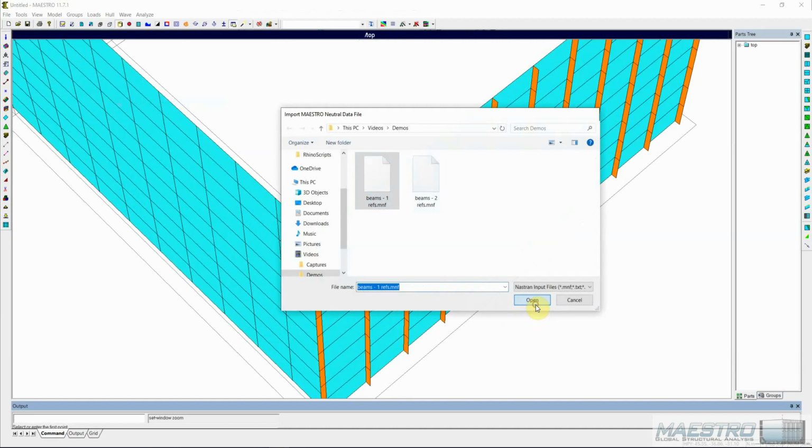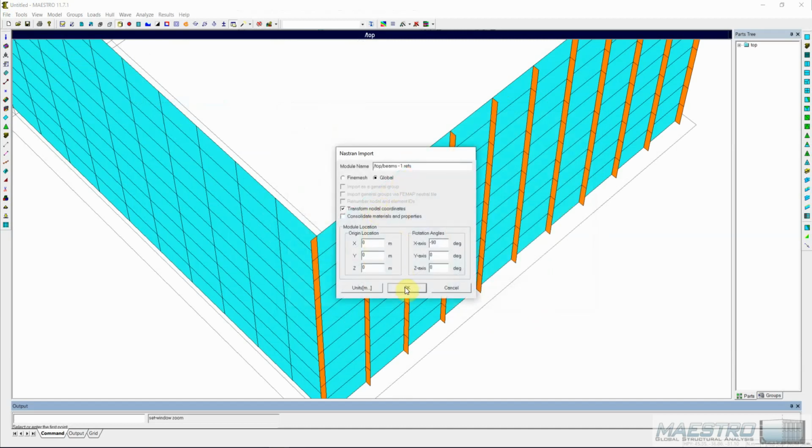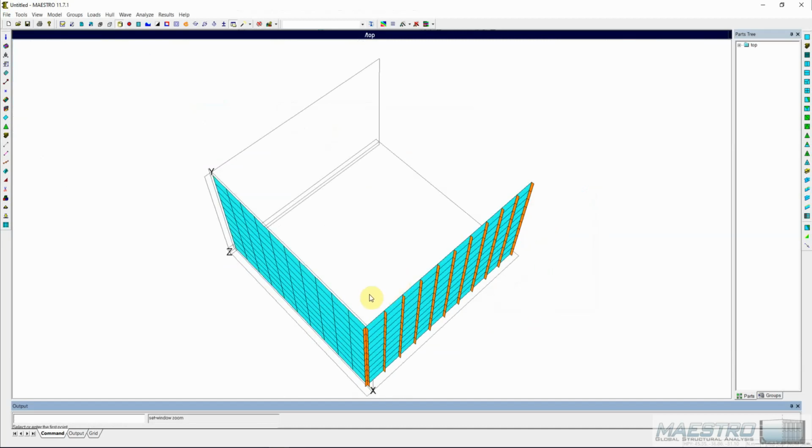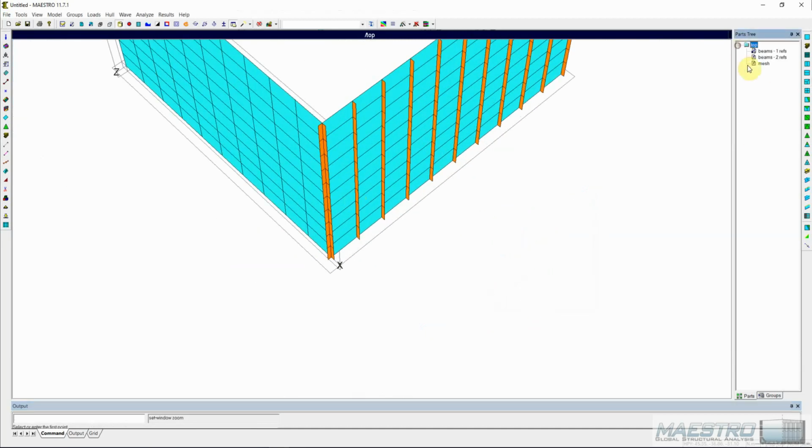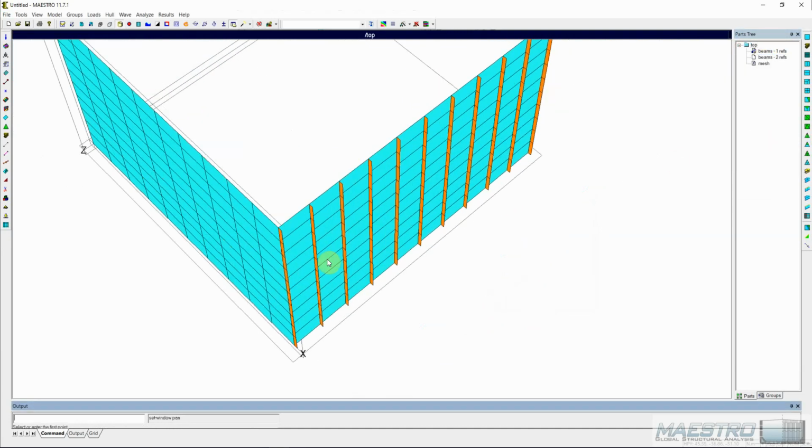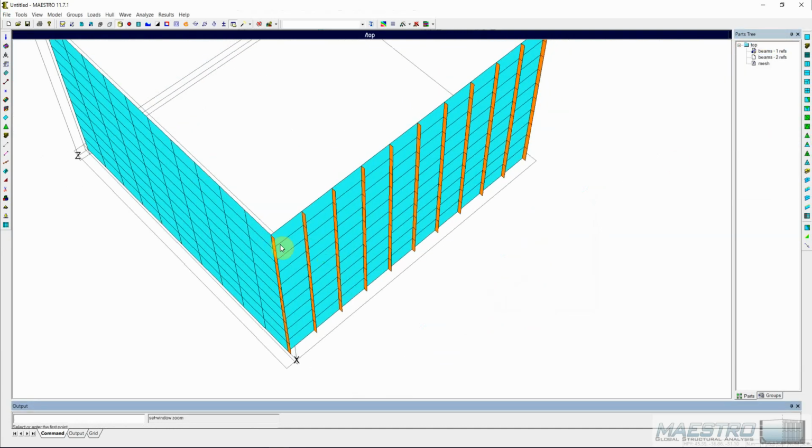And now we'll read in the beams that only had one mesh as an option. And then if we turn off visibility on that first set, we can see that the beam now selected the right orientation. If working with groups of polylines and meshes, an easy way to avoid this situation is to just operate on the transverse bulkheads, longitudinal bulkheads, and decks separately.